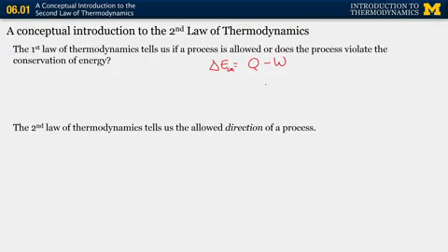And we had a couple of example problems that we did where he said, well, can I have a system that has work transfer in and heat transfer in? And the answer was yes, as long as we have an appropriate change in the energy within the control mass. Now, imagine that same system, and I'll ask you, okay, we have an initial state and a final state. And we've said in this kind of thought experiment that the heat transfer is in and the work transfer is in. Okay, so we know that that essentially makes this right-hand side positive, greater than 0, because we have net heat transfer and net work transfer in. So we know that this final state energy has to be greater than the initial state of the energy.